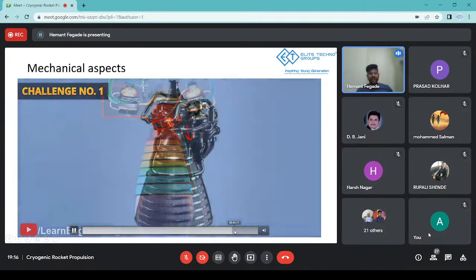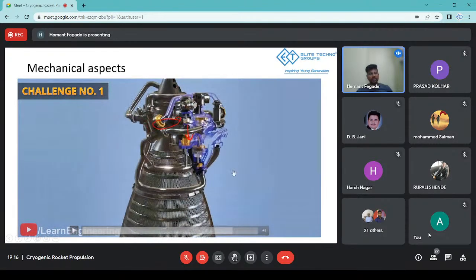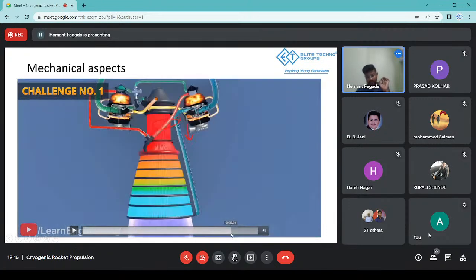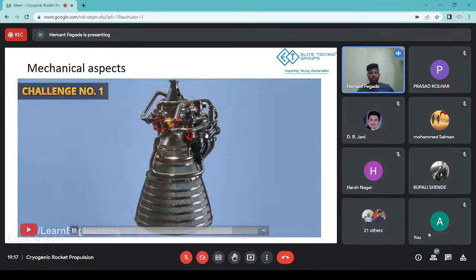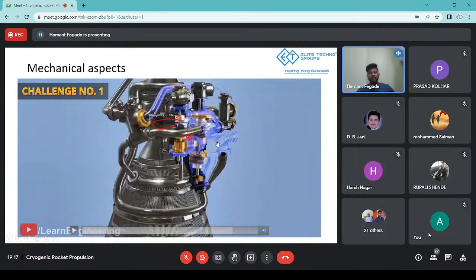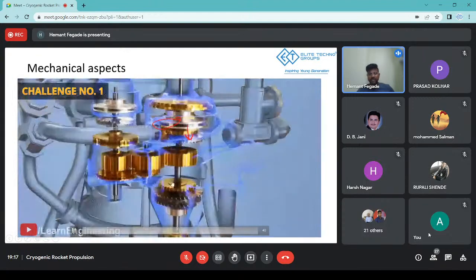The challenge with this kind of thing is still there. Even though you are able to have some amount of control over these turbo pumps, over these combustion chambers, it's not complete control. Things still could go sideways. So some people use another auxiliary system called a gearbox to keep the speed of the impeller and the speed of the turbine separate.